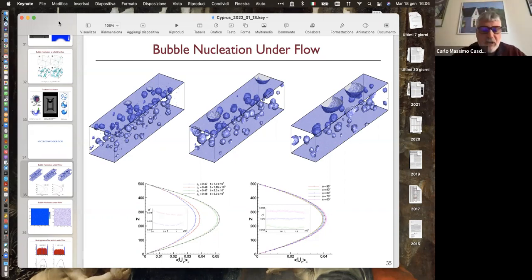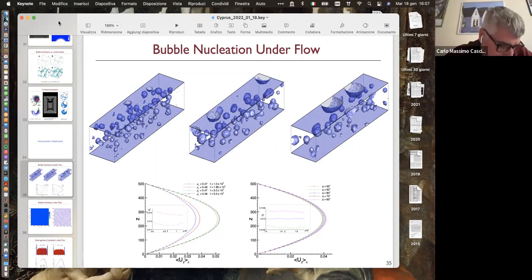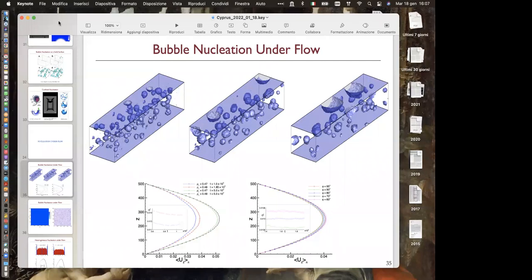The point is the following. You start with the liquid, right? So you have a liquid at a certain density. Then you form a vapor bubble or many vapor bubbles. In the volume occupied by the vapor bubbles, the density is lower. So it means that the liquid gets compressed, so the density of the liquid increases. And overall, you conserve the mass. Does it answer your question?